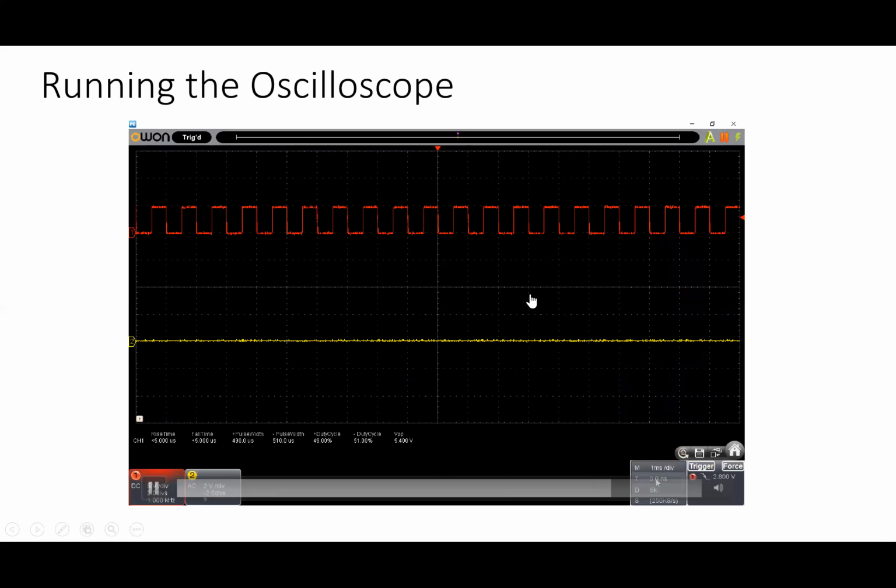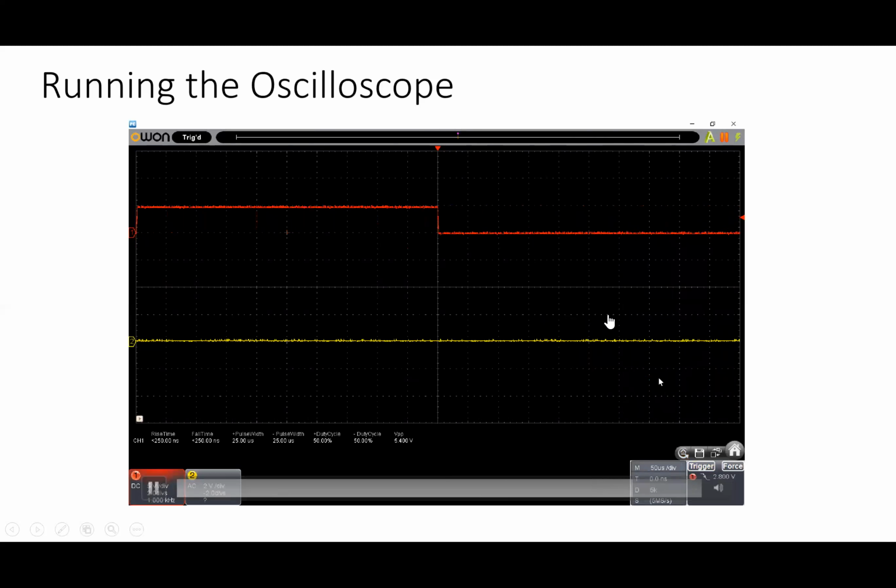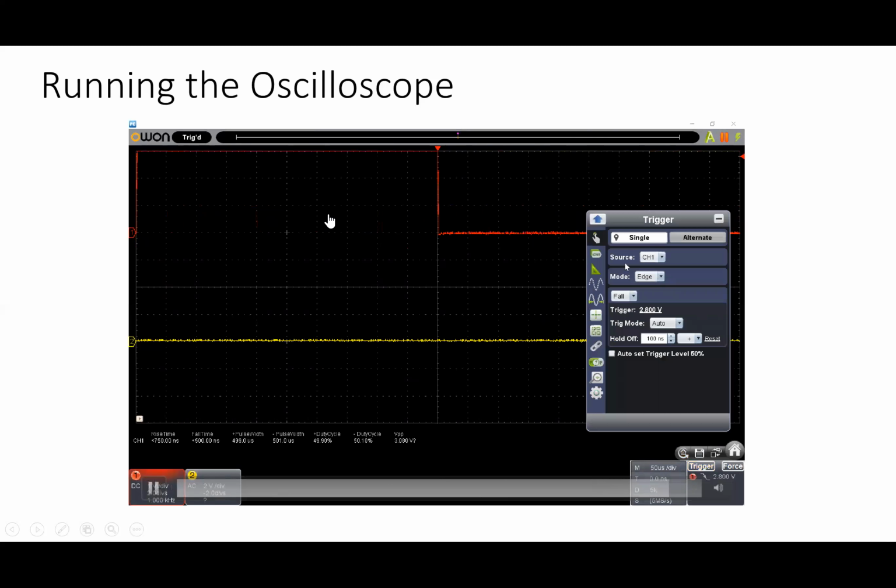Now, I'm going to go over to the time base here and change from 1 millisecond per division up to 50 microseconds per division. And so now you see 1, 2, 3, 4, 5, 6, 7, 8, 9, 10 divisions at 50 microseconds. That is 500 microseconds for 1 pulse width. Of course, 1 millisecond for the whole frequency repeat. Of course, now I've gone out of triggering again because I've just changed the sensitivity down here by clicking on this red box for channel 1. So I've now gone back and I've moved the trigger level into range where this triggers properly.